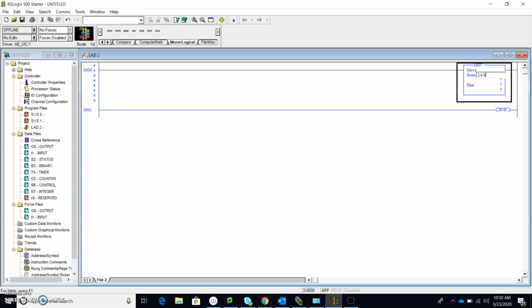If you remember, when we do our discrete inputs and outputs, we'll use a bit, and we know there's 16 bits in a word. Well, on analog, we are using the entire word, which would equal, in decimal format, 32,767.